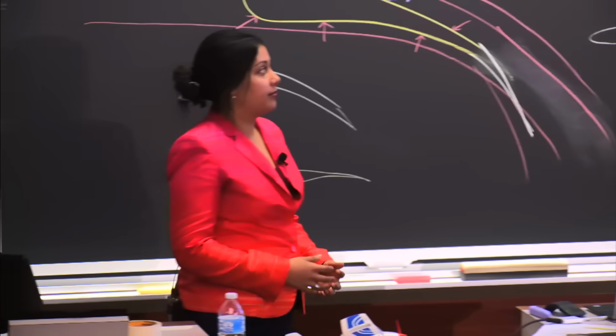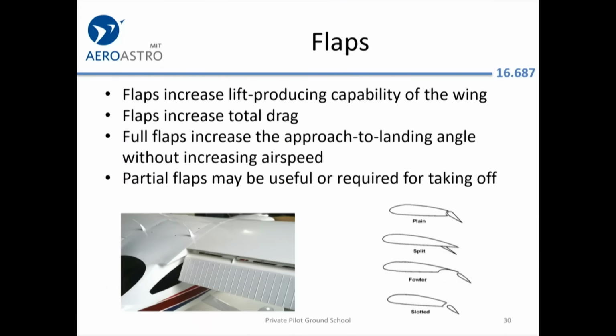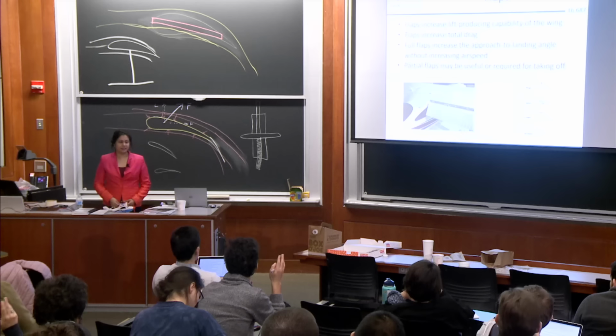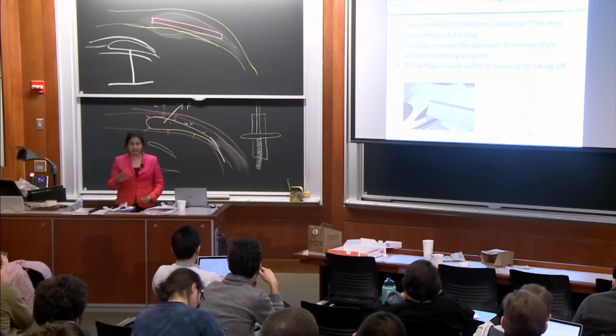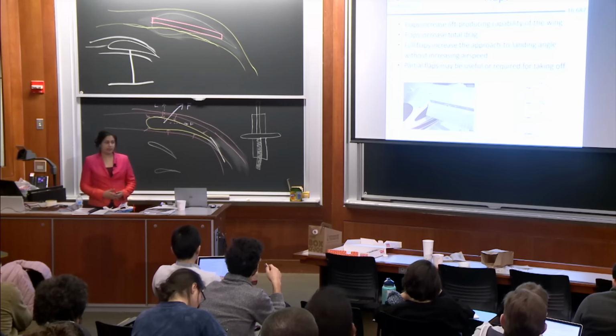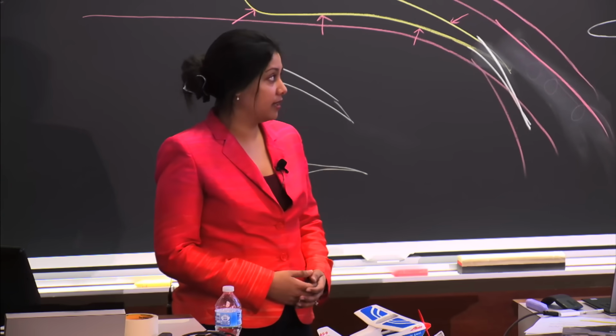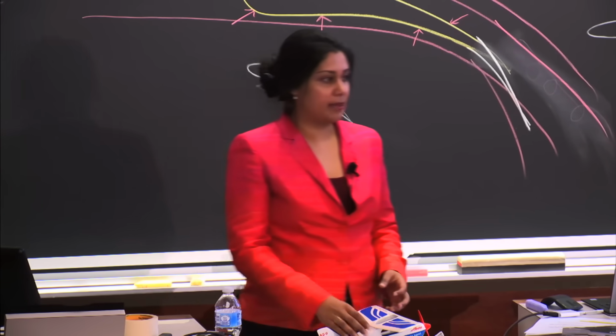So we talked a little bit about flaps, that flaps actually can increase the lift that you're able to produce, but it's a trade-off because it also increases the drag. So when in the course of the flight, takeoff, cruise, or landing, when do you use flaps? Does anyone know? Takeoff and landing.